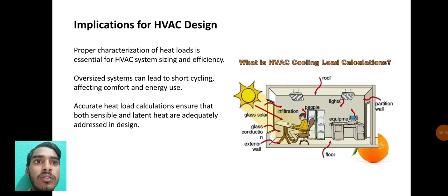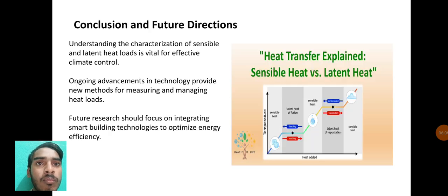Implications for HVAC design. Proper characterization of heat loads is essential for HVAC system sizing and efficiency. Oversized systems can lead to short cycling, affecting comfort and energy use. Accurate heat load calculations ensure that both sensible and latent heat are addressed in design.